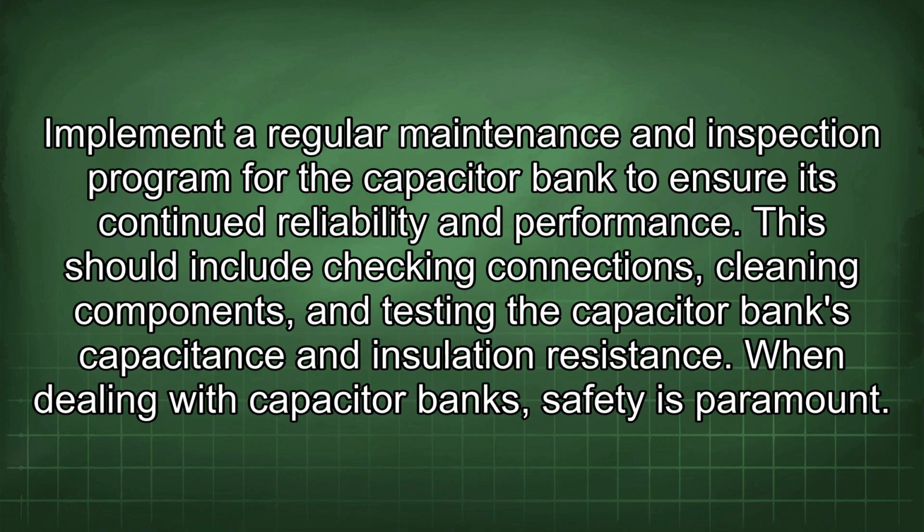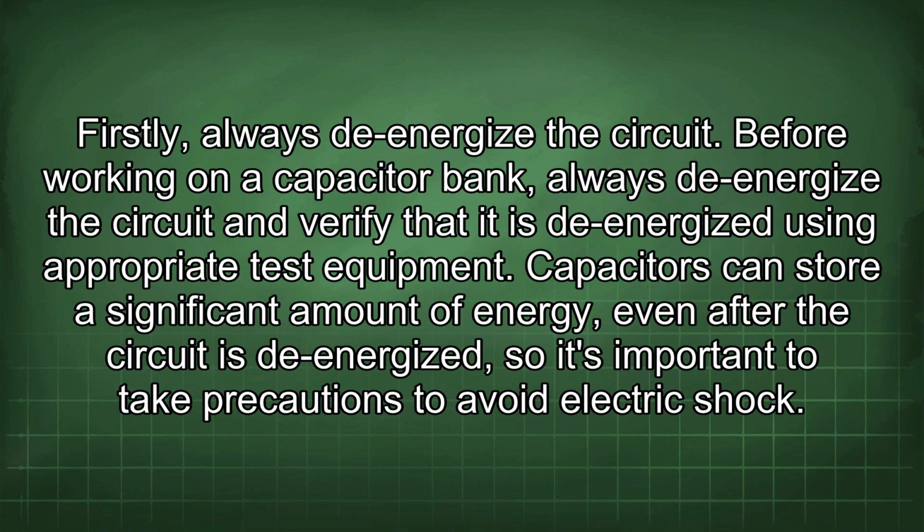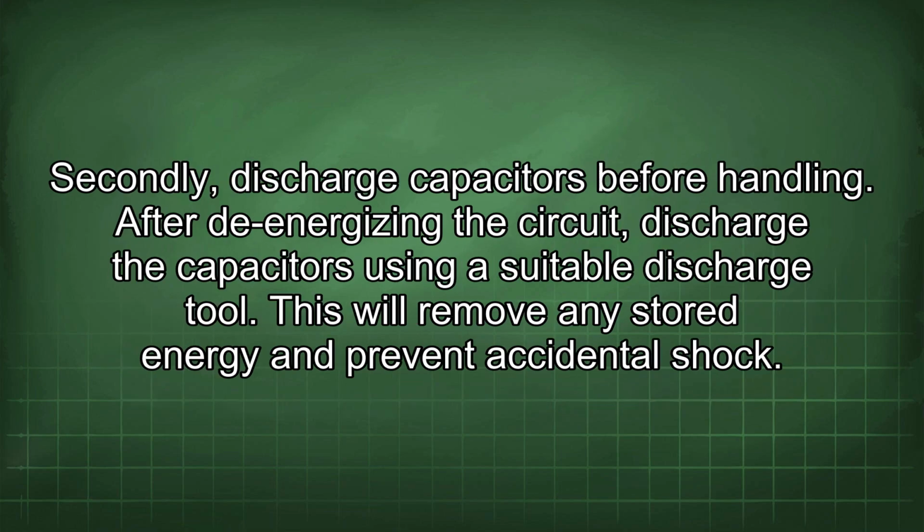When dealing with capacitor banks, safety is paramount. Firstly, always de-energize the circuit. Before working on a capacitor bank, always de-energize the circuit and verify that it is de-energized using appropriate test equipment. Capacitors can store a significant amount of energy even after the circuit is de-energized, so it's important to take precautions to avoid electric shock.